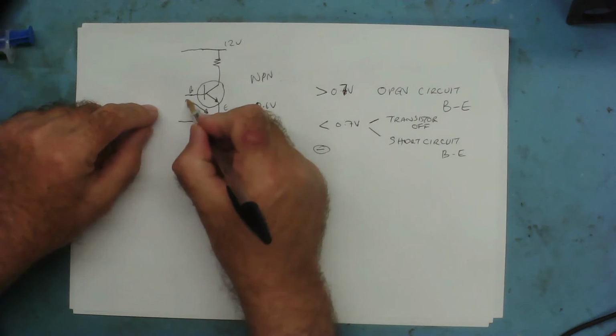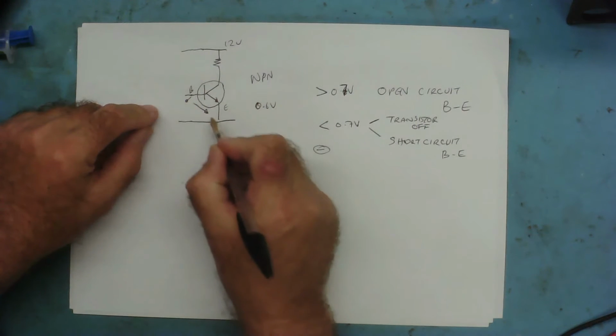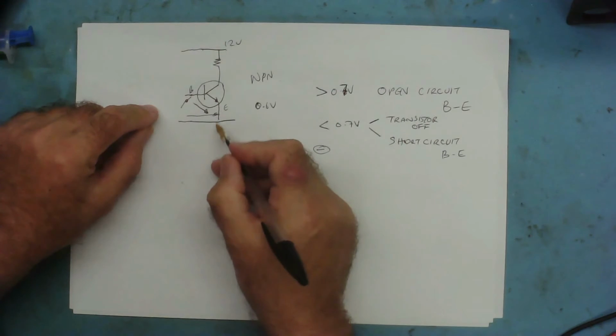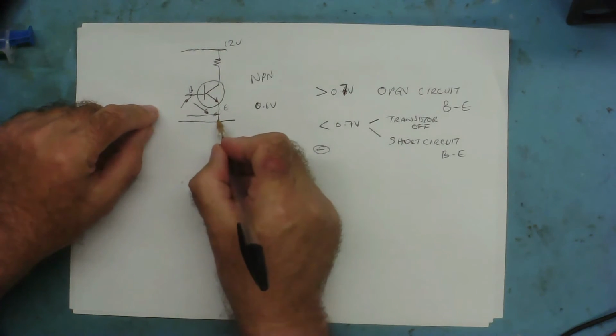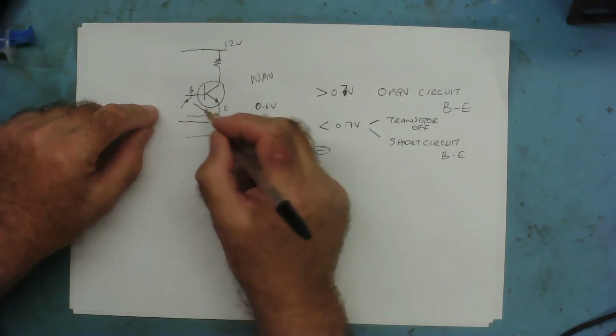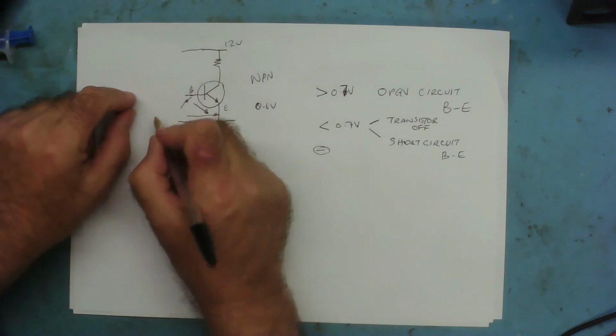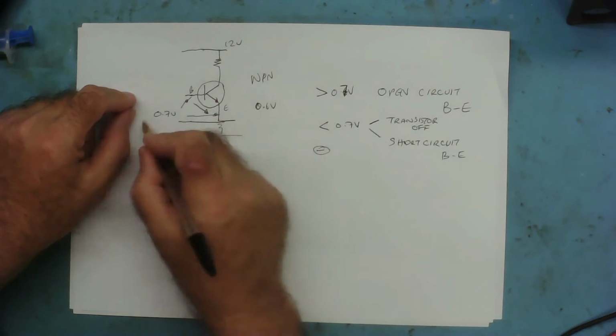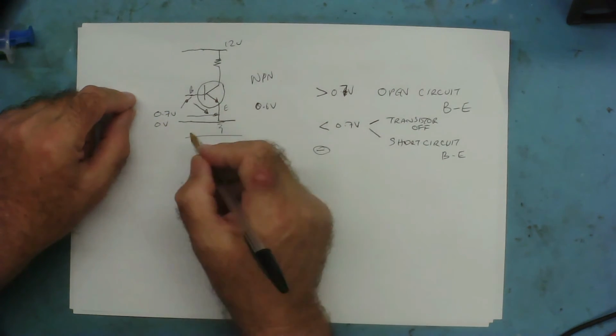So that's measuring the voltage with your meter probes from there to there, straight to the base emitter, not to ground, because there could easily be another resistor in here before ground, yeah. Measuring between the base and the emitter of the transistor, and you either expect to see 0.7 volts if it's fully on, 0 volts or thereabouts if it's off.